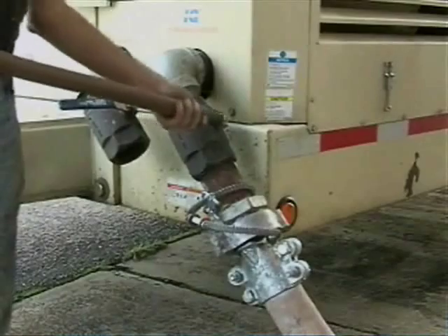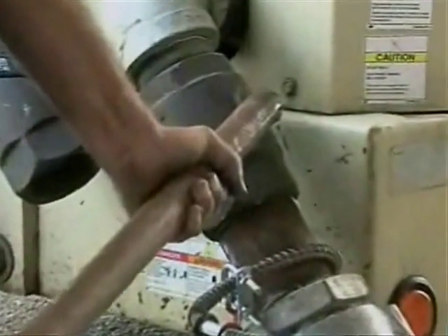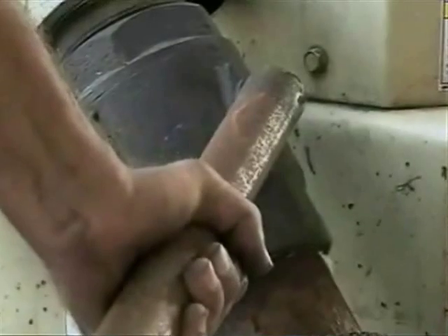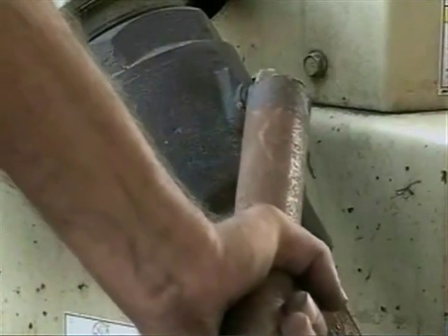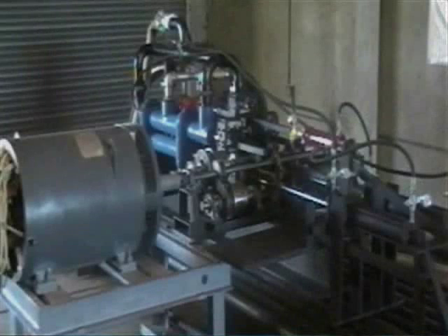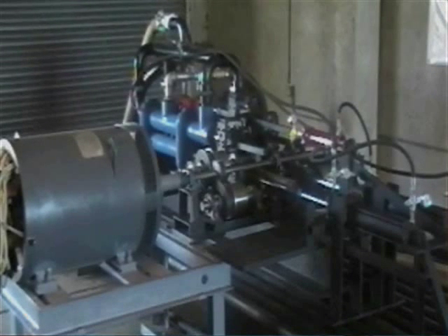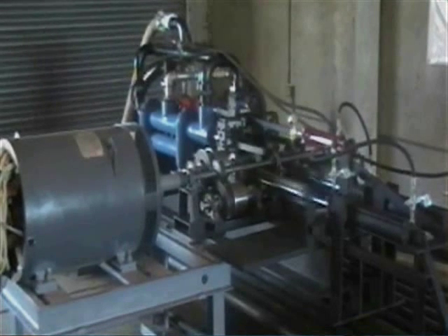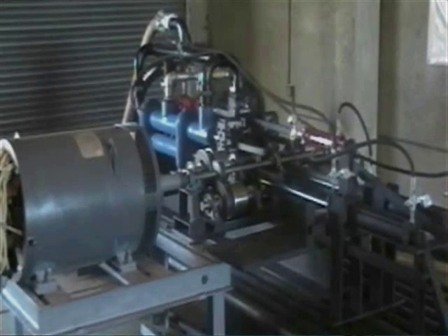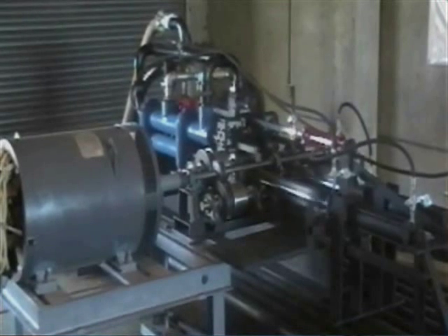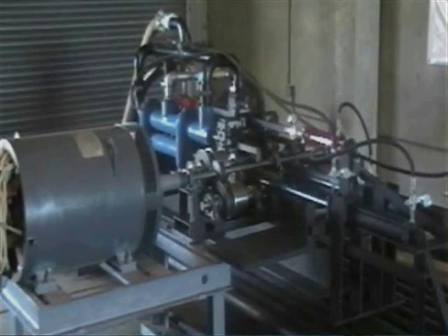The free piston engine is being powered by 47 cubic feet per minute of compressed air at 95 psi, having an inlet temperature of 150 degrees F. Timing is accomplished by pressure changes produced by operation of the piston, using pneumatic shocks that compress a gas in order to stop the forward movement of the pistons, thereby controlling the stroke length. Additionally, the shocks provide energy storage via the pressurized gases that act like a spring to reverse the motion of the piston in the opposite direction.